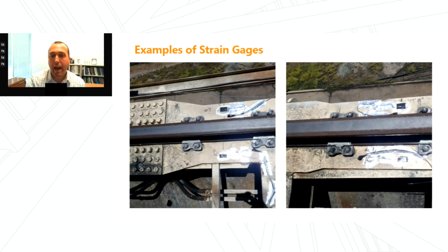Here we're looking at strain gauge location 2 on the right, strain gauge location 3 on the left, and these were critical locations because they're adjacent to flange transitions. The strain gauge locations are the black rectangles that are on the girders just to the right of the transition regions. And they are where the stress ranges are expected to be higher, right adjacent to those splice locations.